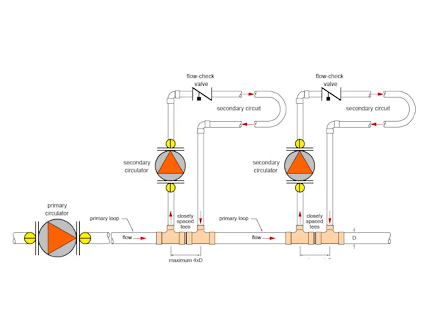Manifold boiler design. Modern compact boilers have a much higher flow resistance than earlier cast iron boilers. Because of this, we need hydraulic separation of circuits. The best form of hydraulic separation is closely spaced T's. You can see two closely spaced T's on this image.